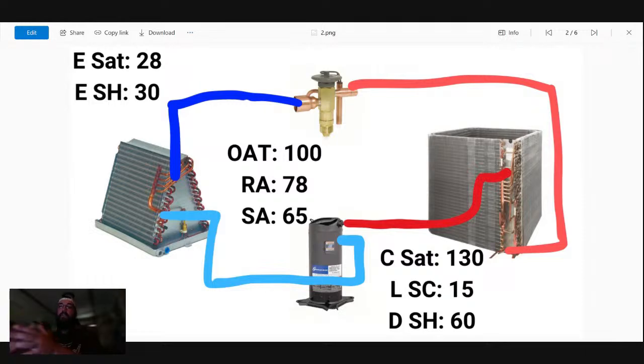Essentially what we did is we made a slight calibration adjustment on the valve, and that got it to where it's now operating within the range we wanted it to. And in some cases, when you start dealing with this issue, you may see a dramatic result like this within 1 revolution. You may not even have to go a full 2. So there's a couple of things here. At this stage, we've made a good call.